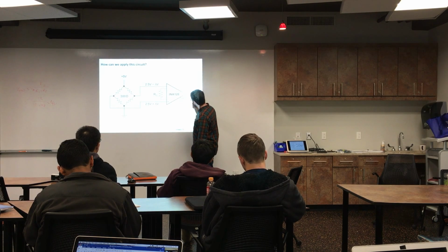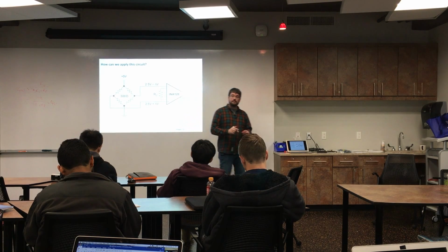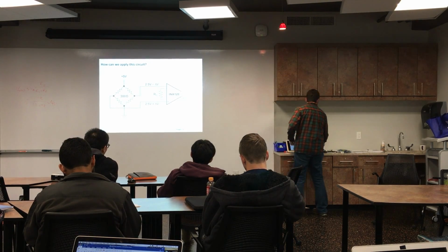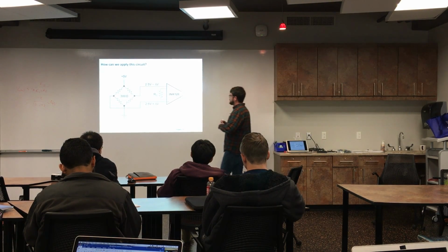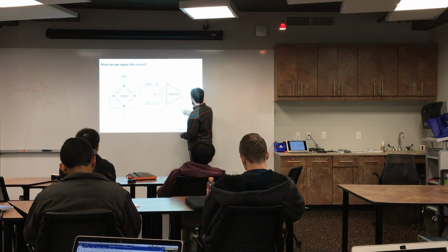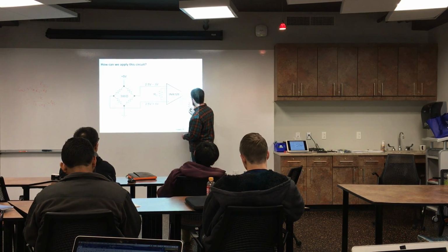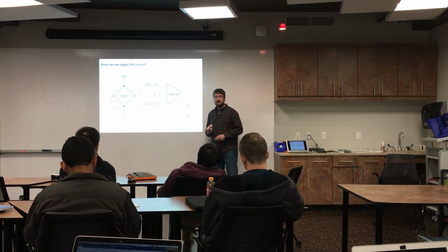Let's do it like this, actually. Make it a little bit clearer. You can't see it. Use a potentiometer, create a voltage divider with it, and put that voltage into the reference terminal. There we go. Plus 5, and do that.